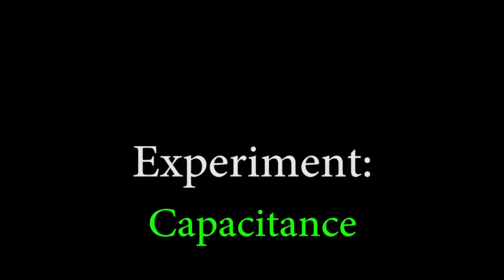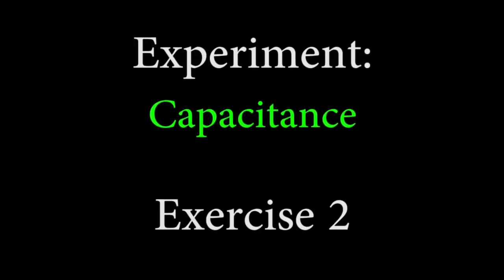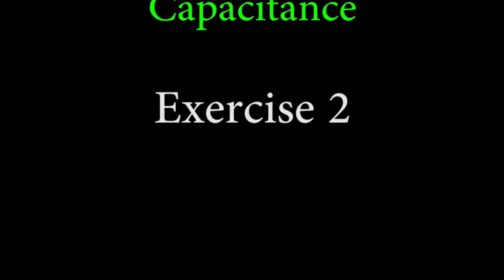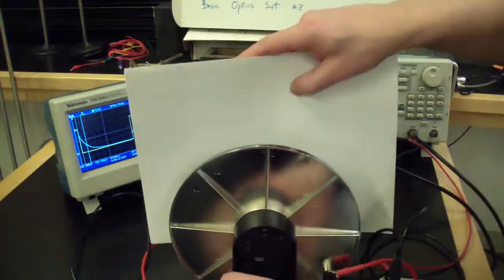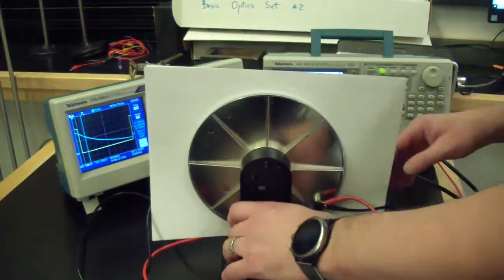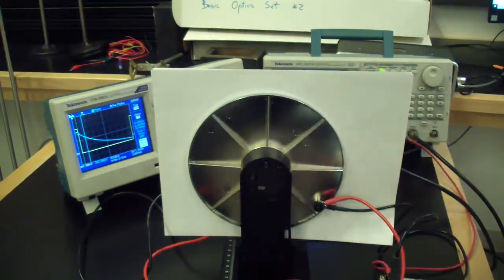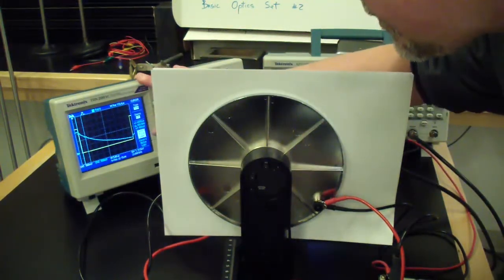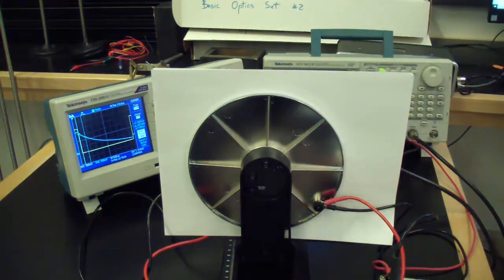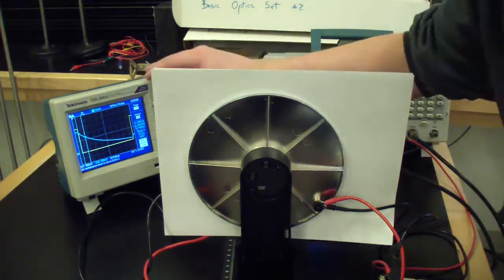In exercise 2, we'll be using different thicknesses of paper as dielectric to fill the capacitor and measuring the capacitance at each separation with and without dielectric. Count out 5 sheets of paper. Insert them between the plates. Close the plates on them, making sure that the plates are tight but not pressing. That is, they will not close further when the paper is removed.